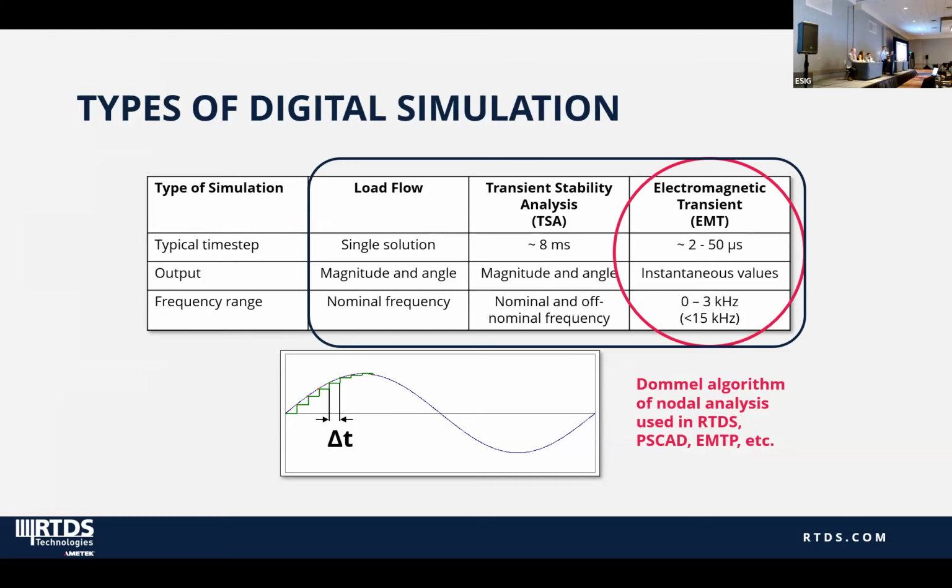The simulation time steps will be in the order of 50 microseconds for a standard AC network, but we can also have the models running, or even portions of the model running with much smaller time steps to be able to incorporate the effects of fast switching converter models.